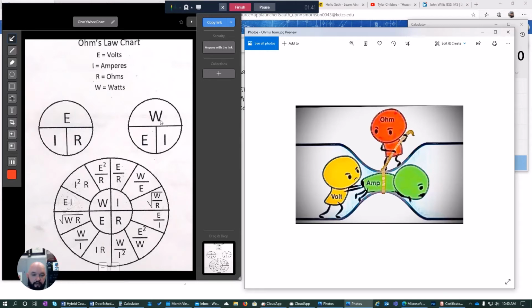Talking about heaters, common examples of measuring the current in heaters: they go in 5 kilowatt sections. A 5 kilowatt heater pulls 20 amps. A 10 kilowatt heater pulls 40 amps. A 15 kilowatt heater pulls 60 amps. A 20 kilowatt heater pulls 80 amps. Those are the most common on the HVAC side.